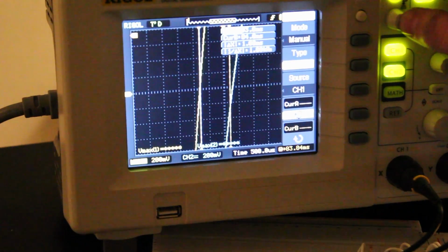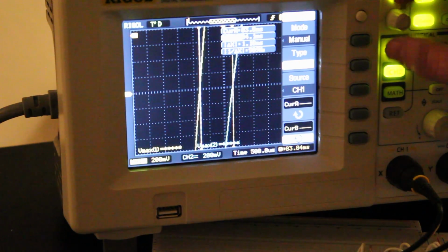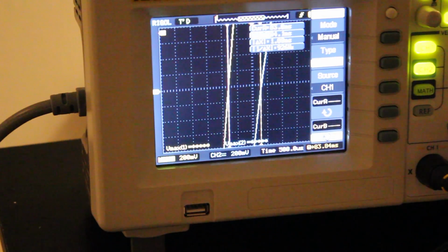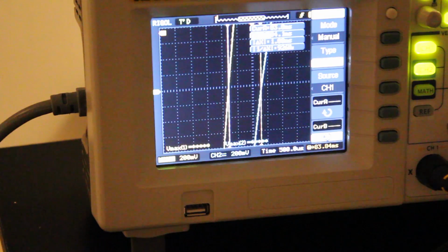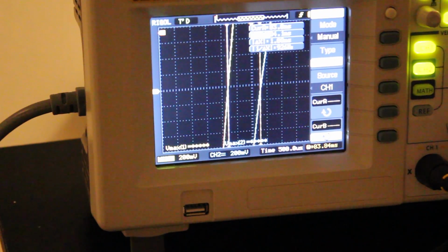We could figure out where that is. And it's telling me that the crossing is about 1 millisecond. Okay, so 0.9 is pretty close to 1 millisecond. So the reason there may be a little bit of error between our calculated versus the observed is because of tolerances. The resistor isn't exactly 1K. These are 5% tolerance resistors. The capacitor is electrolytic, so it's really bad for filtering.